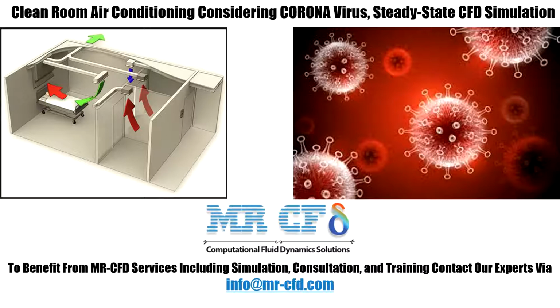And the room environment should be purified in terms of pollution, and a balanced and pleasant temperature should be provided for the thermal comfort of the patient inside the room. There are two main issues in the CFD simulation. The first issue is that the flow of the coronavirus in the respiratory must be defined through the patient's mouth, for which we use a discrete phase model or DPM. Because in this model we track the particles of the coronavirus, we apply this type of view or Lagrangian view in examining the behavior of particles.